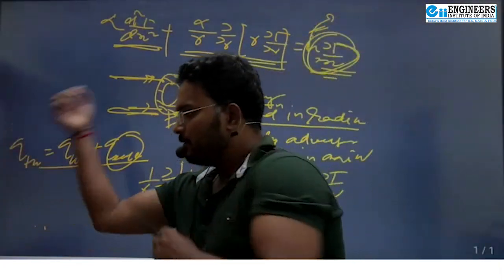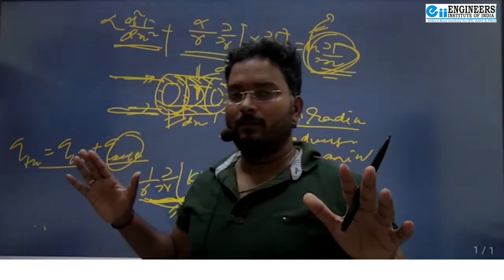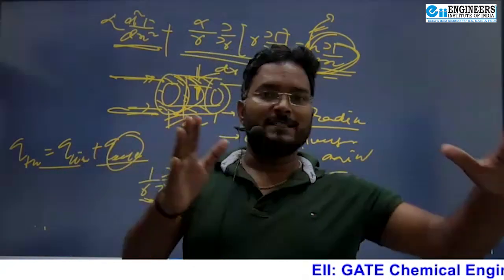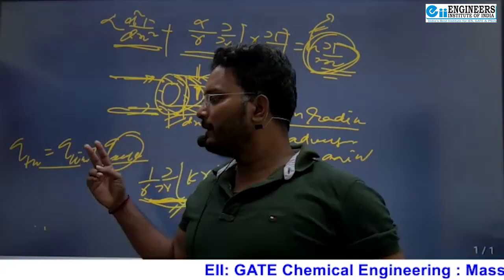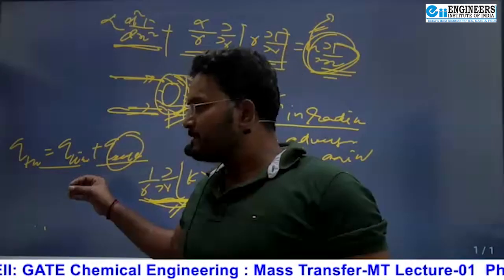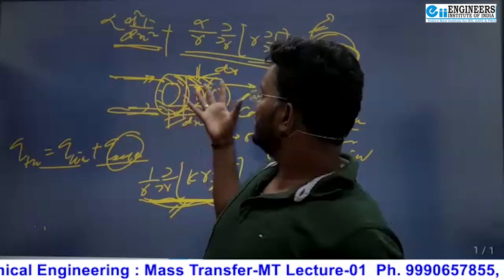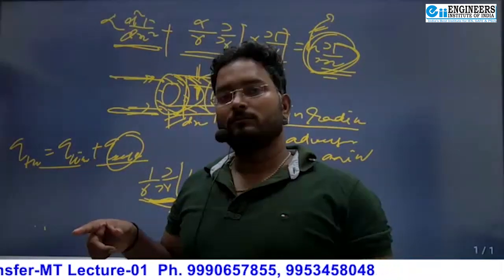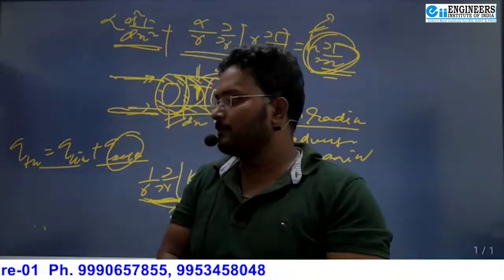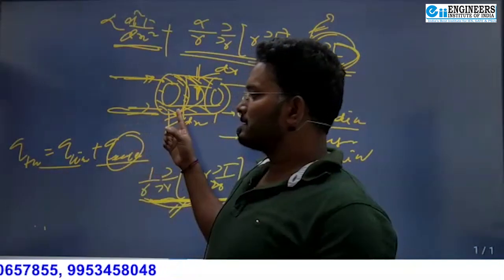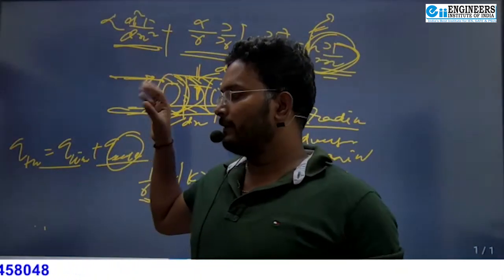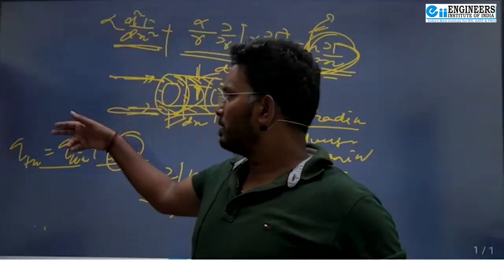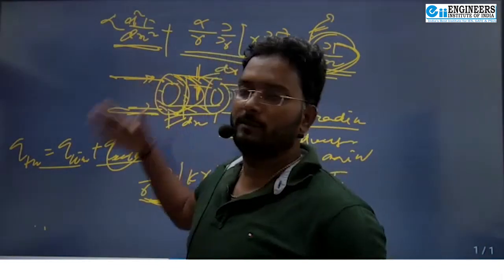So now listen, whenever the fluid is stagnant or in laminar flow, the only two mechanisms there for the heat to be transferred in this example. When the fluid is stagnant, then only one is there, called conduction only. But when the laminar flow is there, then two: one is called the bulk flow mechanism and the second is called the conduction mechanism.